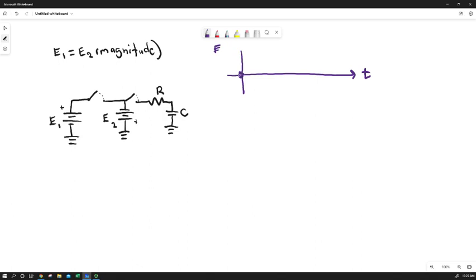So we would start with a voltage equal to 0, and at some point we would go up to our maximum, and for whatever period duration dependent on the frequency, then we would go to negative, whatever our amplitude was, and then come back up. And that would represent one waveform when we got back to here. So we would initially go to, we'll call this E1, and then negative E2, and of course if E1 equals E2, we would have a square wave.